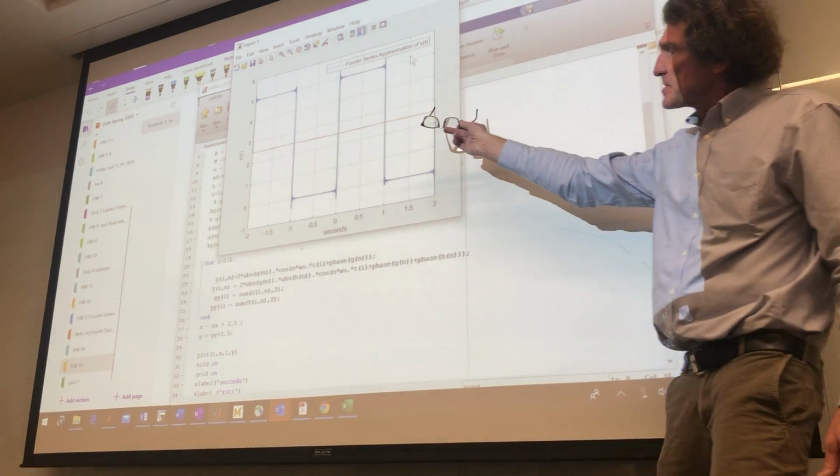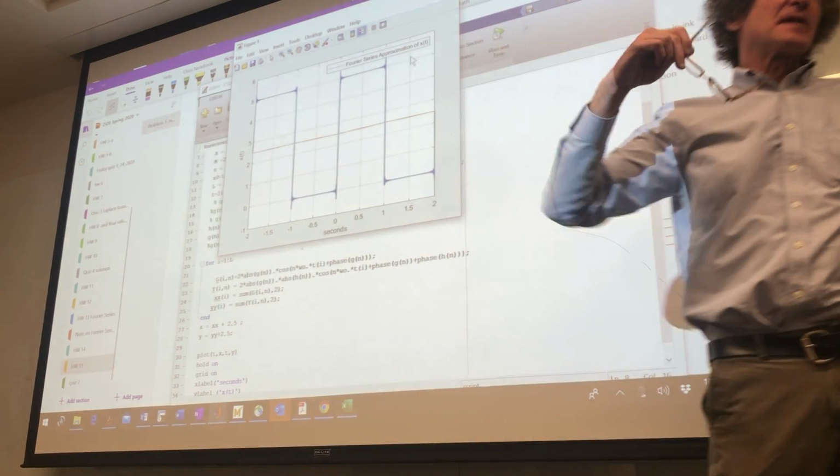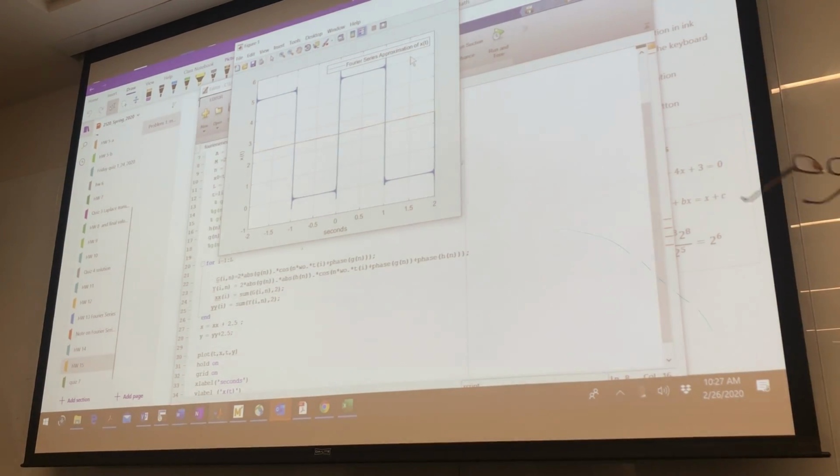Y'all see how that's just the average value now? This kind of gives you a glimpse at how real filtering works. An inductor right here is going to be something where it gets rid of any kind of rapid changes. If you do a source transform here, you could put a voltage of 5 volts in series with a resistance.